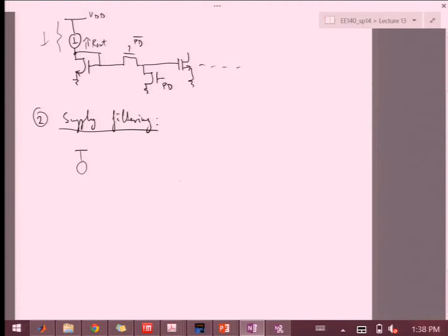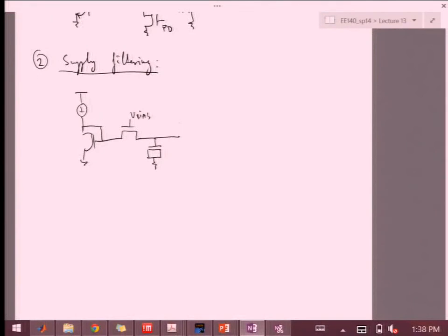And so one way to do this is simply to add, similarly to the power down scheme, a gate here with V bias. And then we can add a FET here whose source and drain are connected together. That one will be in the triode region because source and drain are connected together, so you don't get the pinch off.